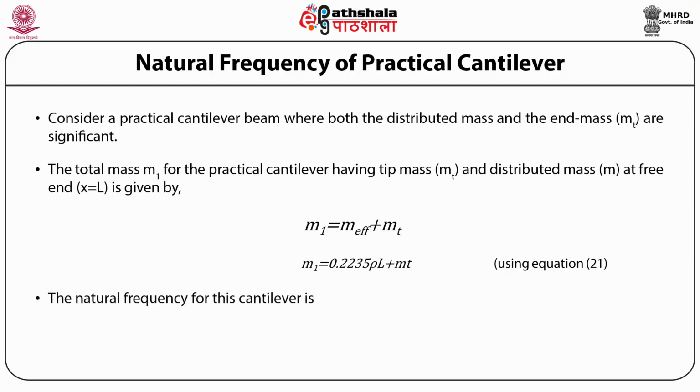Finally, the resonating frequency of the cantilever comes out to be F is equal to 1 upon 2 pi times square root of 3EI upon (0.2235 rho L plus Mt) times L cube.